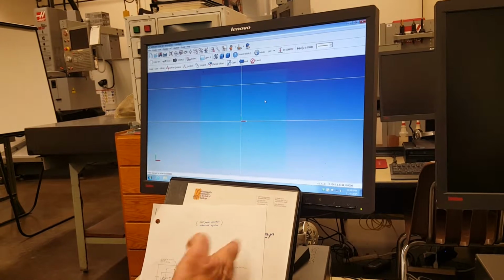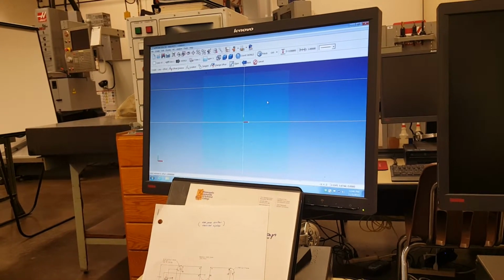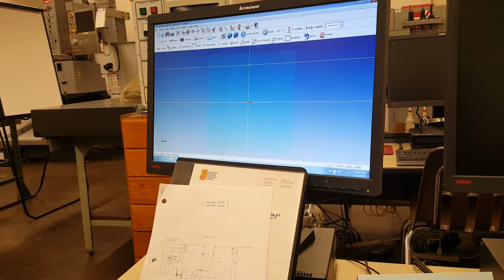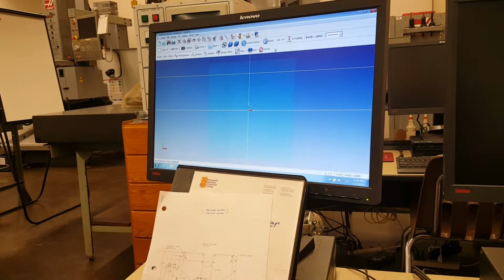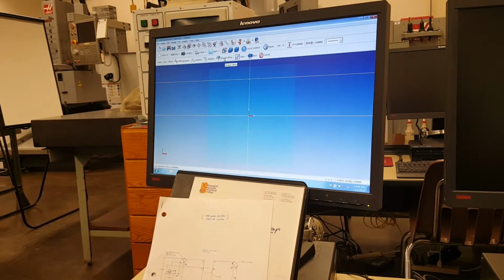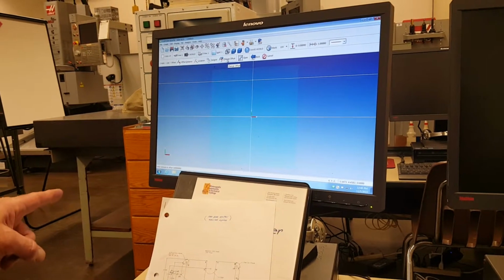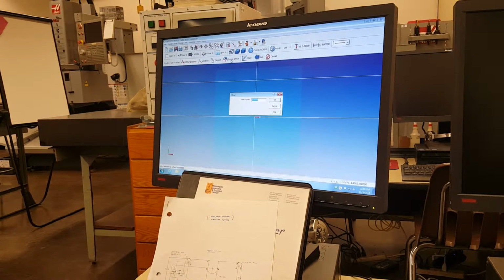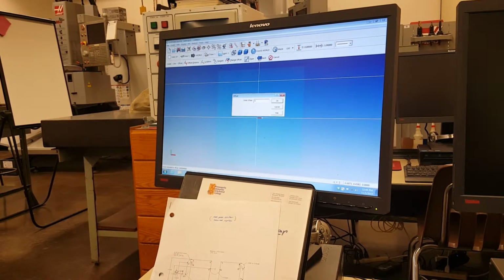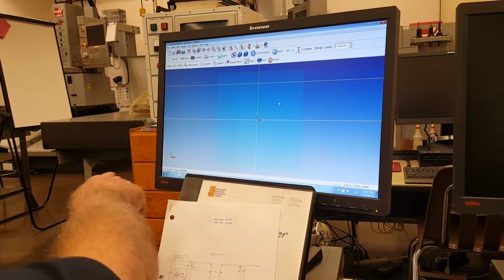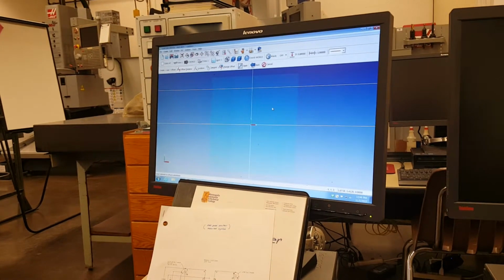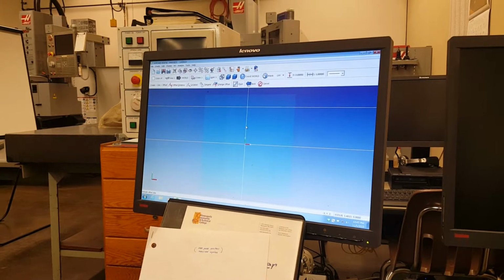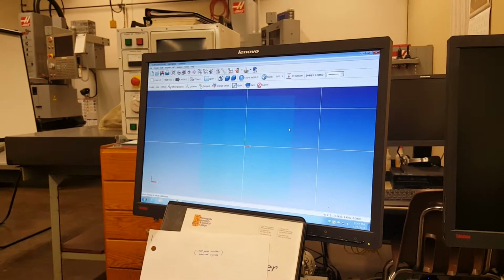Okay. Now I want to get the vertical line, so I'm going to go back, offset, change my offset because it says 3 down there to the full width, which is 6, and hit OK. It'll ask me the same questions. What element do I want to offset? Well, it's this one. What side? That side. Okay.